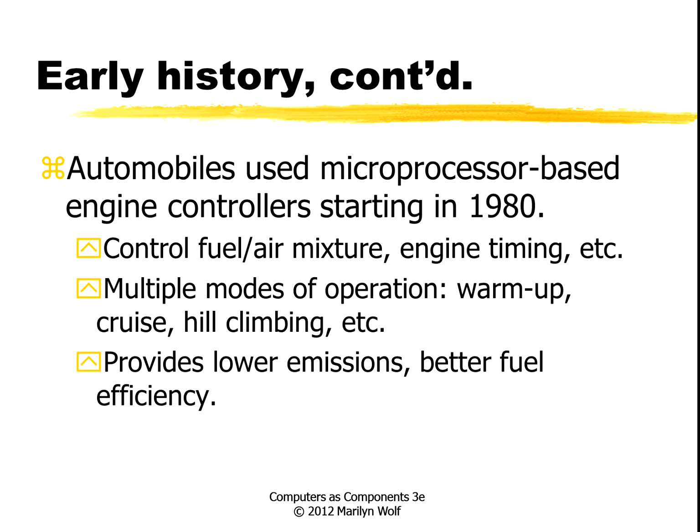Cars started to use microprocessor-based engine controllers in the 1980s. They moved from mechanical controllers, which included things like distributor caps, to having microprocessors that actually determined the fuel-air mixture, determined when the spark plugs fired, actually controlled the engine. Not only did they control the basic operations, but they had several modes of operation.